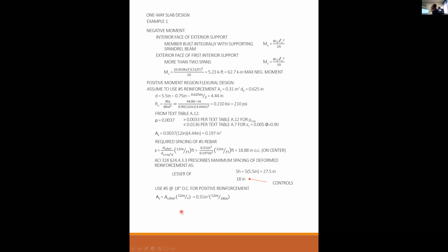Okay, so now what we're going to do is we're going to reverse this, because if you notice, we did our minimum steel check, our maximum steel check, but we have not done our strength comparison, our phi Mn greater than Mu check. We haven't done that yet in all this work. So in order to do that, I need to know what is the actual area of steel that I am providing. Not the area of steel required here, but the area of steel that I am providing.